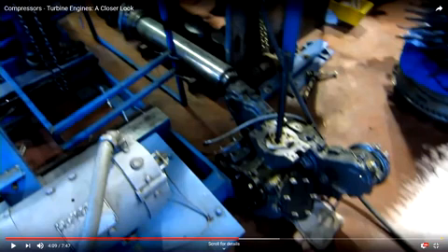And also you can see that the rotor and the stator have to be machined with high precision. They have to be made at the right position, and also made in the right way, which later you will see. It cannot be totally fixed to the rod. It has to have some free play in order for these things to run properly. So the whole process has to have high precision machining involved, and that makes this type of engine more expensive. All right, let's continue.